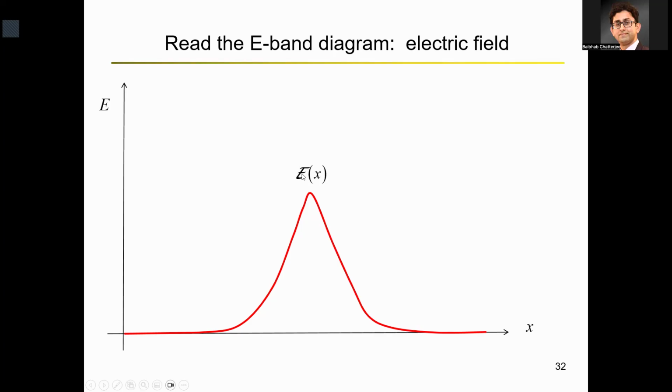And according to the electric field, you'll have a built-in potential. There would always be a built-in potential around that junction, which is very important in some of your device physics classes. We'll not go into the details of that built-in potential in this particular class, but this is the reason. If you look back to your device physics classes and try to correlate, you'll understand this: because your electric field, which is the derivative of that energy band diagram, has a non-zero value around the junction and zero value around the two ends, it's near the junction where you create that built-in electric field and built-in potential.